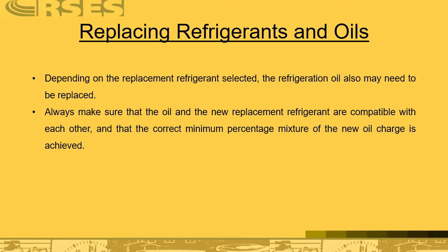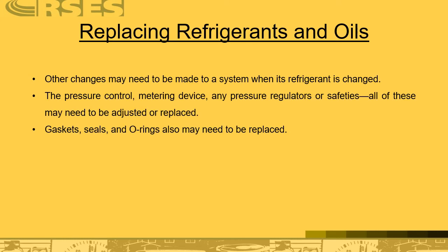I'm just going to tell you that. I have done that many, many years ago. I no longer do that. If the system requires a refrigerant change, you're just better off to price up new equipment that already has the new compressor with the proper oil that will accept a refrigerant such as R410A.